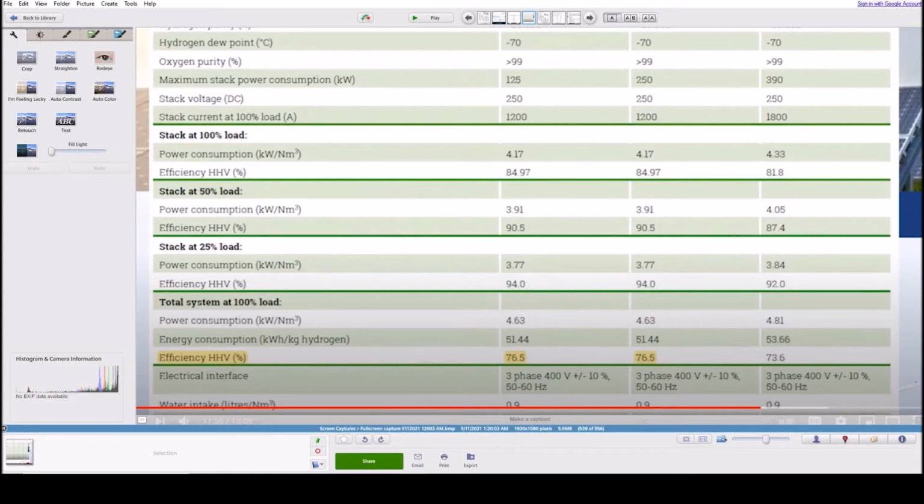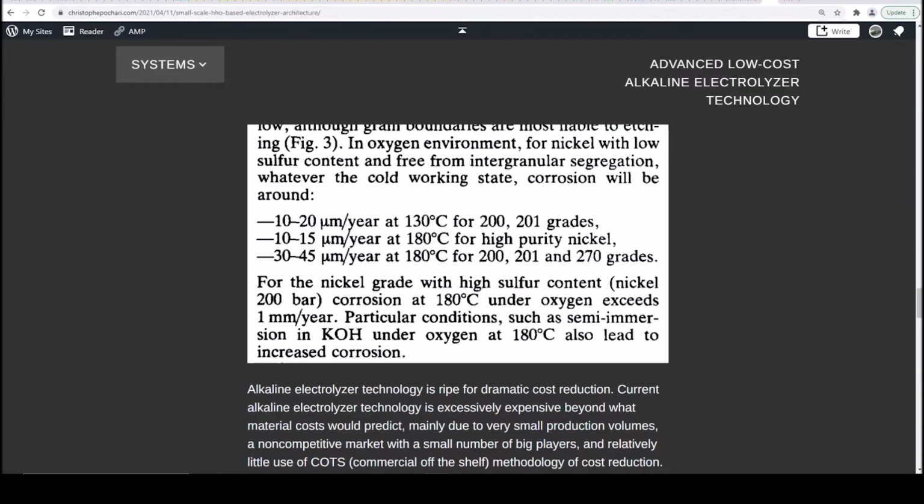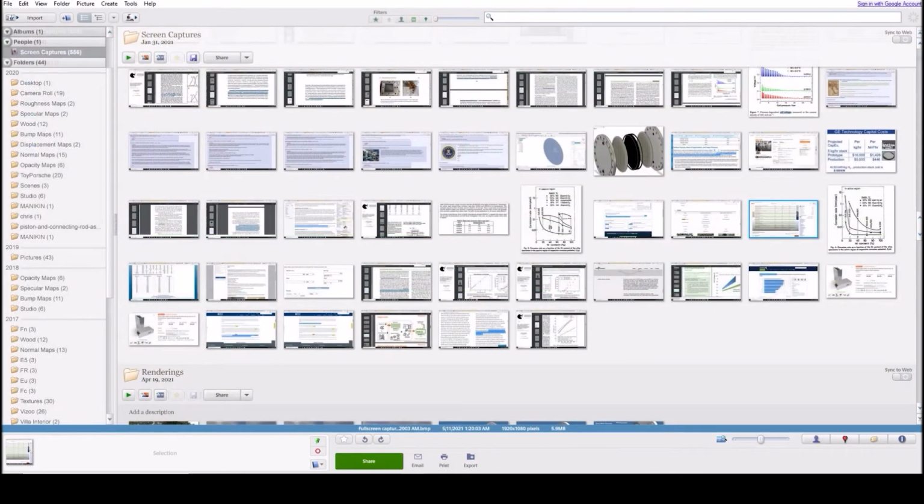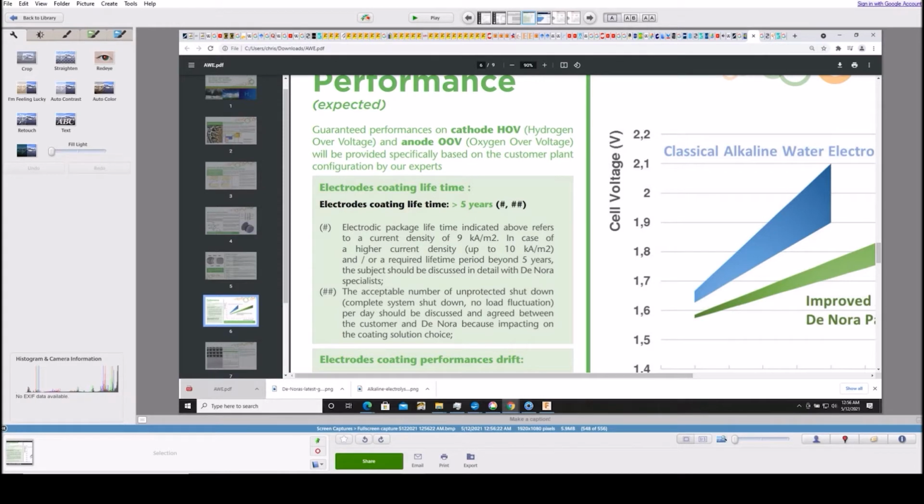3.9 divided by 0.082 is 47. So 47 is a pretty typical number if you run them at 100%. And again, that's because if we assume their cell loading is up to 9, if you run it at half, so 5 times 1.6, right? It's 8. So that's why I size it at 7. So I size it even less.